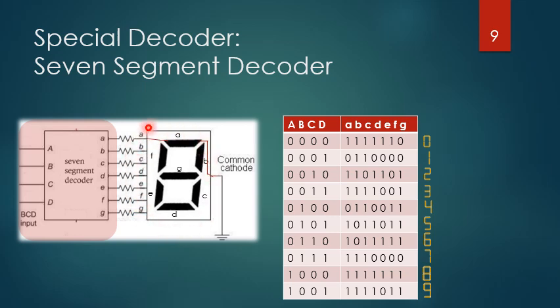In this case, the device connecting to it is a 7-segment display. So the 7-bit output here will represent the on and off of the segments on the 7-segment display, and the character to be displayed will correspond to the binary number received.